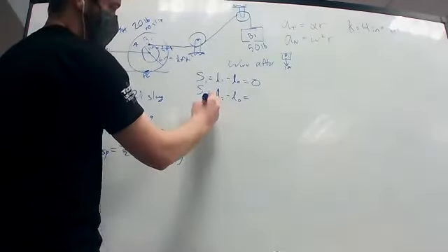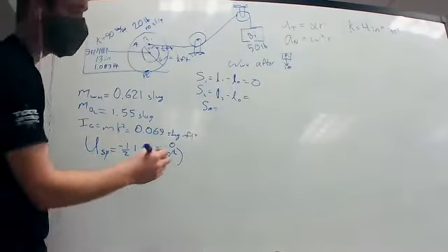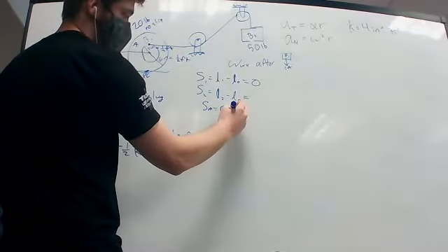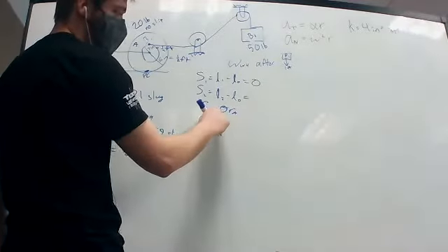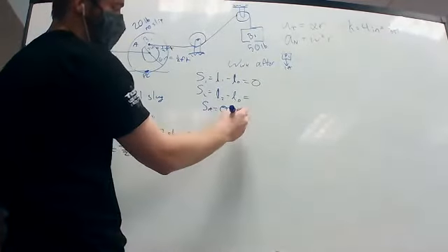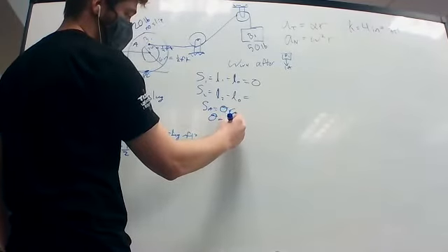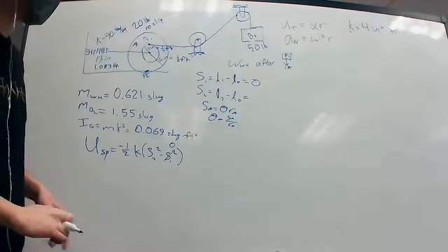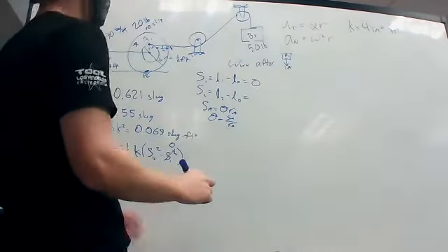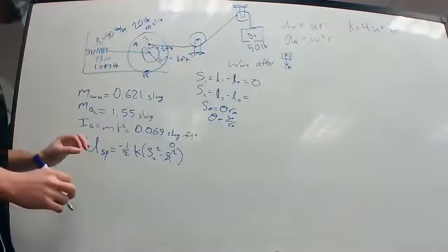So SA is going to be equal to theta RA. And we can rearrange this to say theta is equal to SA over RA. And we can say that SA is 1 foot, because if this block moves 1 foot, the wheel must also move 1 foot.